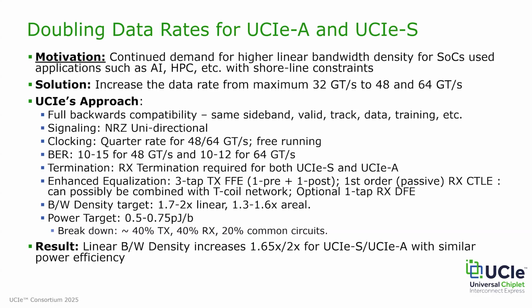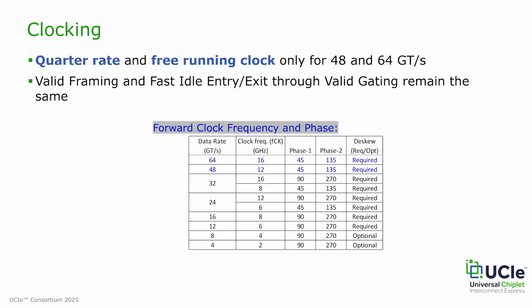if you need additional signal conditioning. And we'll see in the next slide, we made some enhancements to the existing link training state machine to perform these IO optimizations and equalization preset selection to establish the desired eye margins. And with all of these changes, we have the doubling of the data rate and bandwidth density while keeping power efficiency about flat, that we will see later.